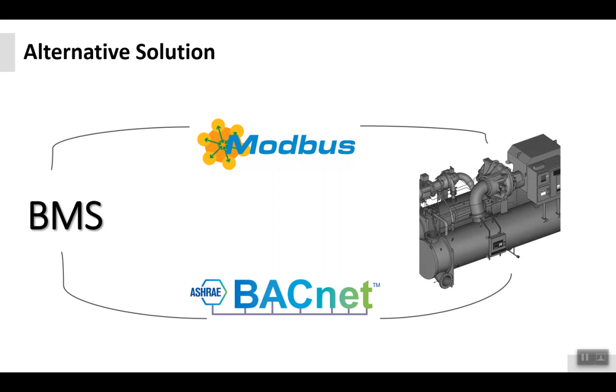So you can communicate from the monitoring level in BMS to the chiller directly, or from the control level to the chiller directly. For Modbus, you should have the register table of the chiller and related information to communicate between the BMS side and Modbus. And for BACnet, you should have the register table and a list of the BACnet objects. Then you can communicate with the chiller.